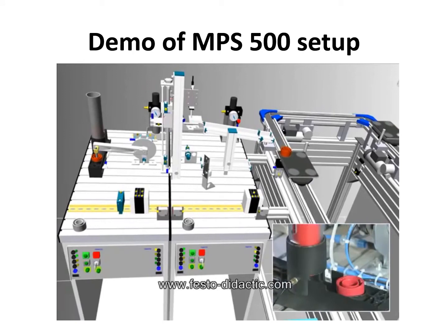Okay, so now the pallet arrived. So you could see at the same time what's happening in the real system. Here is the magazine, and the piston basically feeds the part forward. Okay, so now the part is outside of the magazine, and we have a vacuum here that picks the part, and the swivel, which is a semi-rotary pneumatic actuator, will move the part to the elevator, which is located on the testing station. Again, this one is the distribution station, and this one is a testing station.